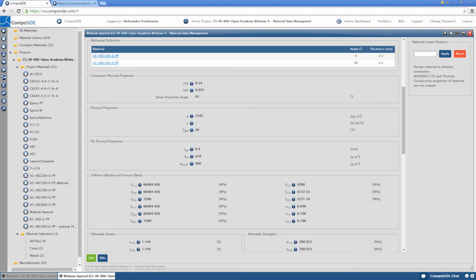There's one more question: can you lock project materials from modification? Only partially. It can be done through roles and permissions. So if you don't want things to be changed, you need to allocate certain roles to your users. You can make them guests, for instance. Of course, there is a way to lock it. If you think that your project is finished, you can archive your projects, and then no modifications can be applied to any elements, including materials.